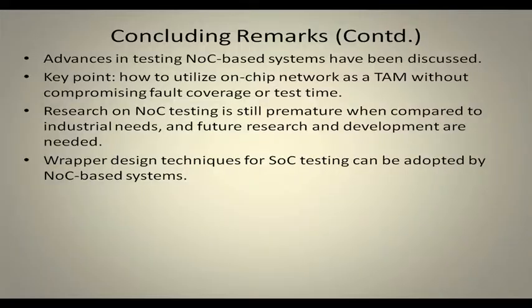Wrapper design techniques for SoC testing can be adopted for NoC based systems, but we have also seen that the 1500 wrapper needs to be modified for NoC testing. That is to be done.